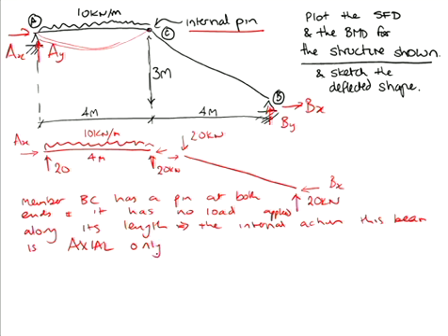So this member, it's like me holding my pen with 2 pin ends, okay? If I try and apply a force that's not in line with the member, it will move down. So thus the only load this member can carry is an axial load. So if we go back to our member orientation here, it is 3 metres high and 4 metres across, so this is our good old 3-4-5 triangle.